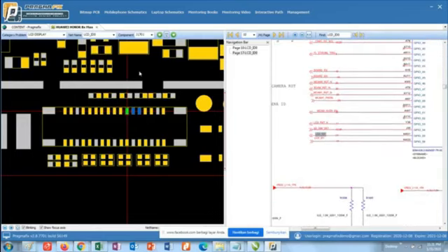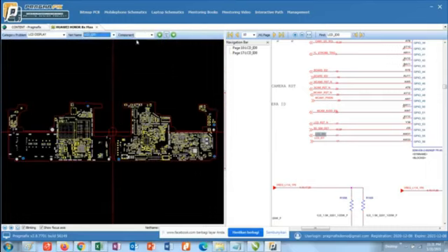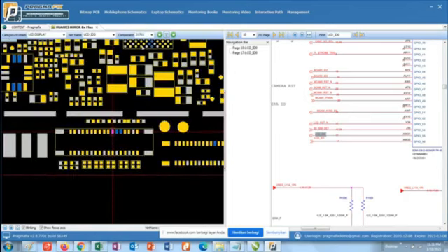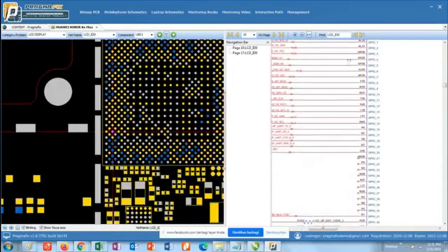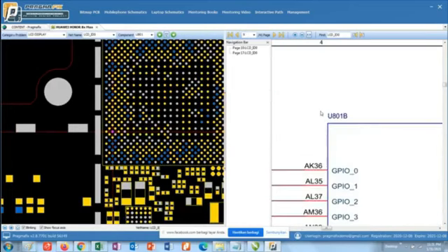Yes, that's what we describe in the image on the left, the bitmap. So if we choose LCD data 0, our choice has only two components, that is J1701 and U801. If we click directly, it automatically shows the point, which is U801, the processor or CPU. It is definitely the same, must be accurate. Let's see, we continue here.